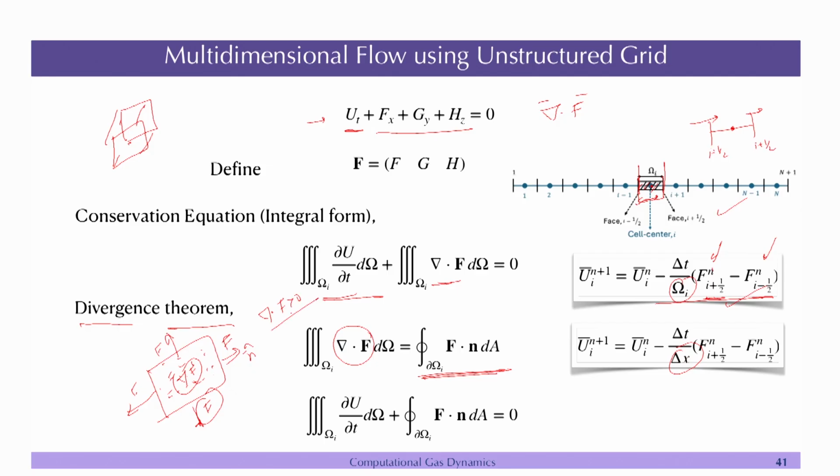In a fluid dynamical sense, if there is a divergence of u which is greater than 0, that means there is an expansion. If del dot u is less than 0, then it is basically compression, right. So, that is why in compressible flow these terms are not 0, and in incompressible flow, del dot u is equal to 0, right.